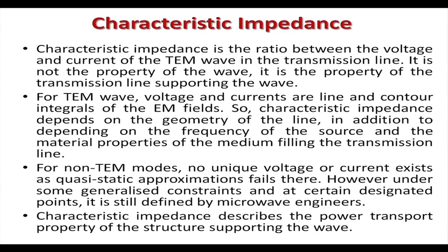Now, characteristic impedance, I have already said earlier, the concept from two-port network, is basically an impedance so that both sides you see impedance match. Now, for a non-symmetric network it is image impedance, for a symmetric network it is characteristic impedance. So, if you terminate by characteristic impedance, you see that the input impedance is the same. So, from the source to the line, the power transfer is the same. Similarly, if you put the source impedance equal to the characteristic impedance of the line, then at the load side there will be a match. So, the maximum power transfer will take place.